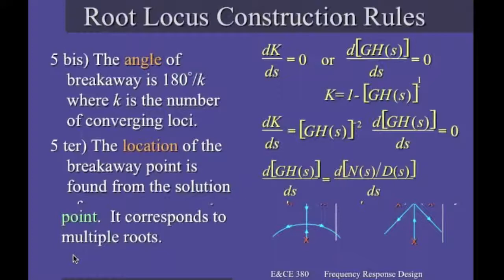Anyway, it is easy to make the other calculations, or in a simpler way to understand the graph, because please remember that the root locus is always symmetrical. So if there is a trajectory emerging with an angle of plus 45, for sure we will have another trajectory emerging with an angle of minus 45, which is this one.